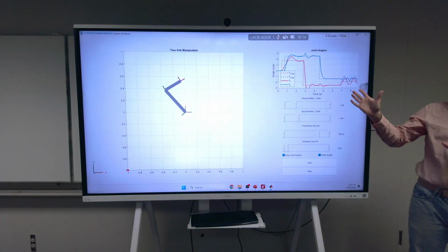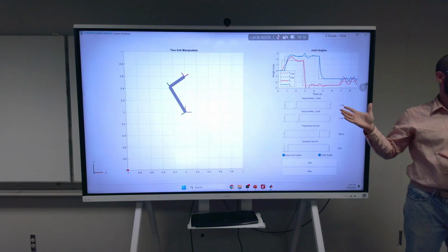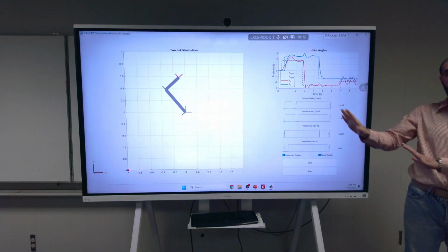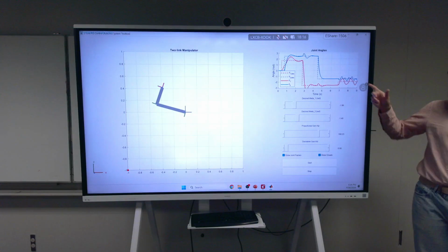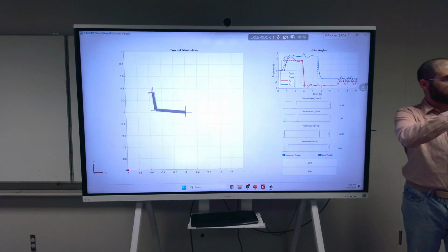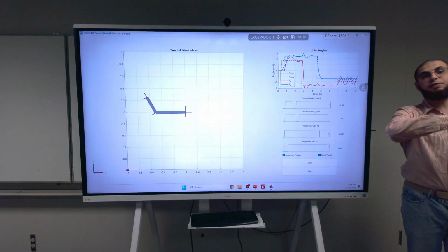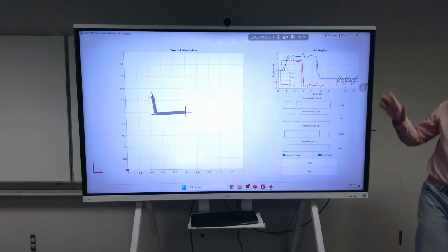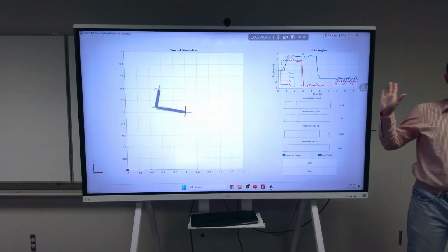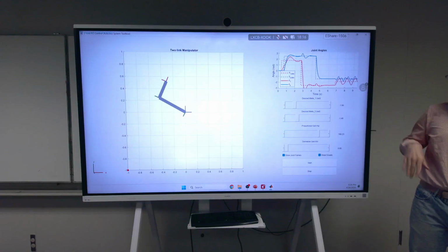Because again, just to remind you, there is no friction here. So B of x2 in this simulation is equal to 0. If I added the friction, you would have seen all of this oscillation damp out. Even if it's very slow, it's still called global asymptotically stable. However, this is not global asymptotic stability. This is just stability.